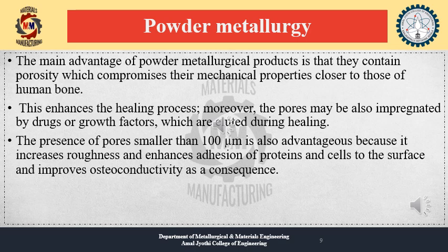Powder metallurgy. The main advantage of powder metallurgy products is that they contain porosity, which brings their mechanical properties closer to those of human bone. This enhances the healing process. Moreover, the pores may also be impregnated by drugs or growth factors which are eluted during healing. The presence of pores smaller than 100 micrometers is also advantageous because it increases roughness and enhances adhesion of proteins and cells to the surface, and improves osteoconductivity as a consequence.